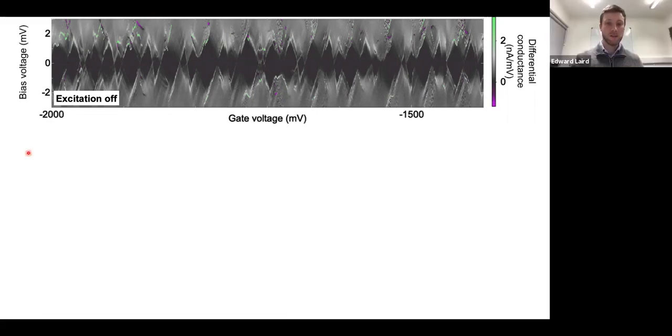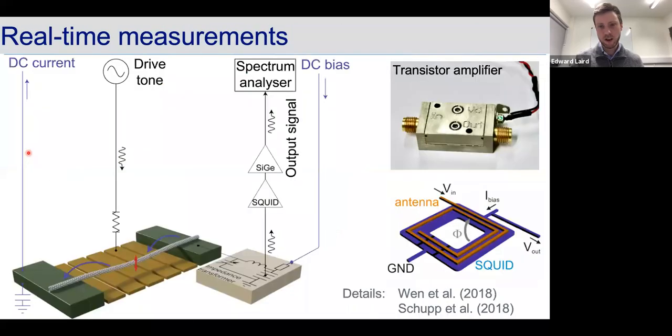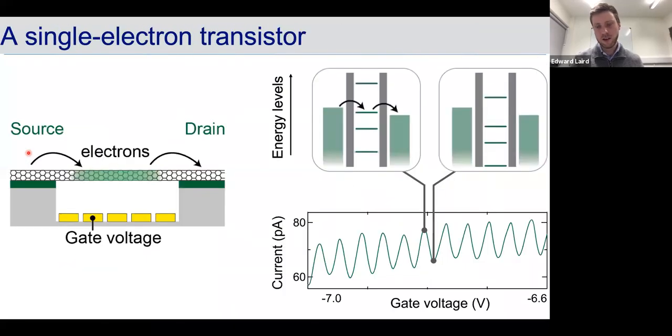Yes. Well, there are two things that contribute to the width of a Coulomb peak. One is temperature, and the other is the tunnel rate, the energy uncertainty that comes because you have lifetime broadening. And I suspect in our device, at least in this curve, it's lifetime broadening that probably dominates. And again, the reason is that we cannot tune the barriers to be as opaque as we would like.